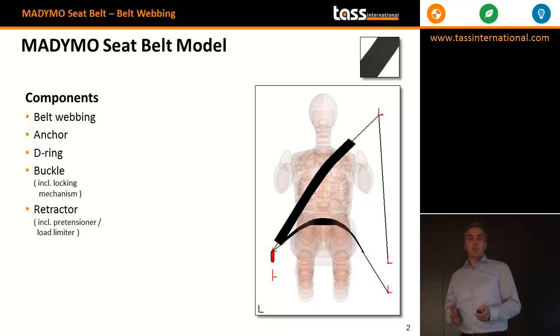But also switch sensor, switch logic, switch multiport and switch control system. And the actuators in the MADYMO model are basically your elements like belt retractor, belt pretensioner and belt load limiter. This is where the switches are called, and if the switch changes, then the belt retractor, for instance, will make sure that the belt spool is locked.